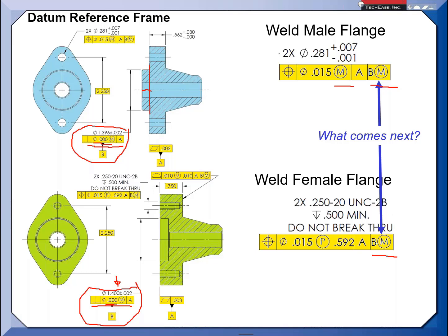I've applied 0. But if I was not comfortable with that possibility, or the risk was high, of MMCs of both features coming in, I can inherently modify the limits, so I automatically build in a gap of non-interference. I can readjust my MMC size, make it a little bit smaller, or adjust it so that my hole doesn't get that small either. That's an engineering decision. But have I done this on some of my designs? Yeah, I've driven it down to 0. And you may have boundaries. If both parts come in at that, it might be a problem. Did that kind of help?